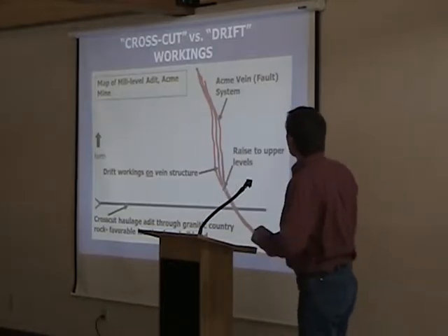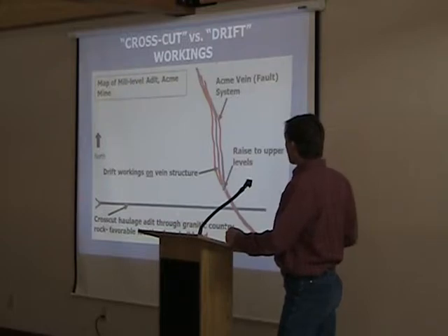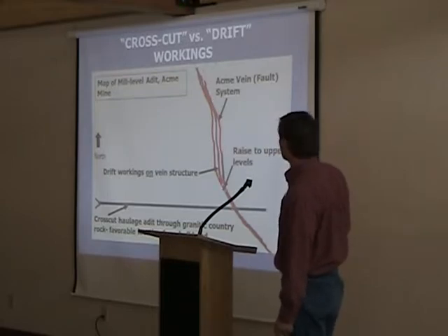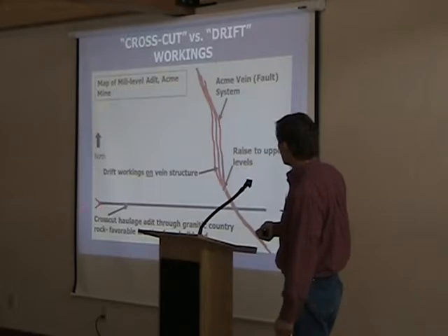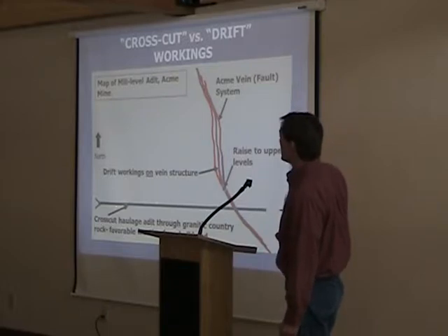So what's the crosscut versus drifting that we've realized works well? Well, if you're on a crosscut, you're usually in pretty good, better rock than what we normally find along these veins or these hydrothermally altered, sometimes fault fissure systems here. So if looking on a map of a mine, you can see that this is my lowest adit, and I've got this nice long crosscut haulage tunnel back to the vein workings. This could be something that might be feasible for bulkheading.